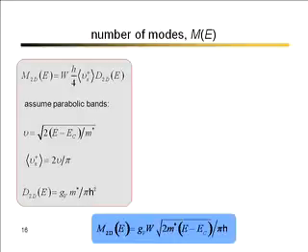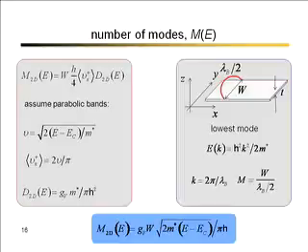Okay, so we can just plug numbers into this expression, and we can find out what this quantity M is, right here. And we get an expression for it. And that's what it is. So that's all we need to know to work out the IV characteristics. But we can look at it in another way to get a little more feel for what this quantity is. So this is my MOSFET channel. It has a width W. This comes out of the page in most of the sketches that I drew of the MOSFET. It has a length L.